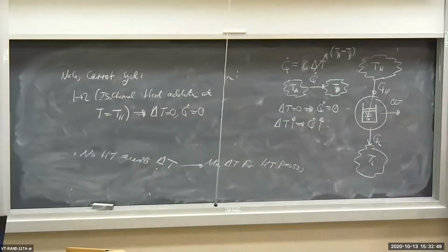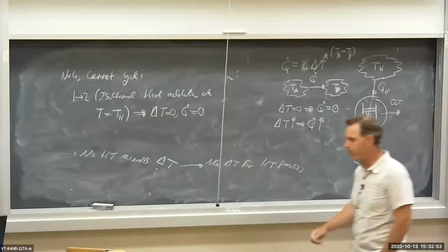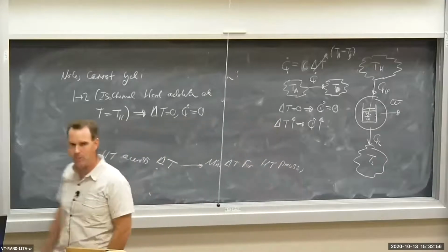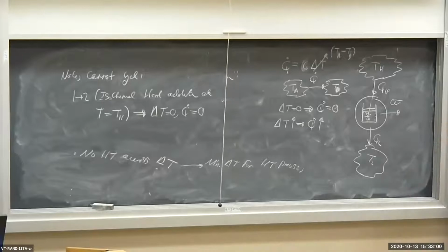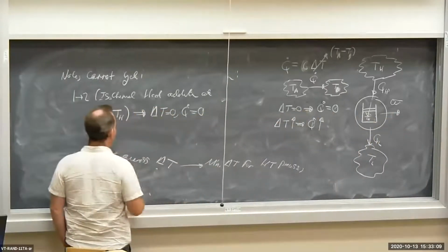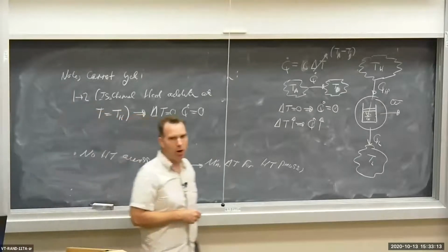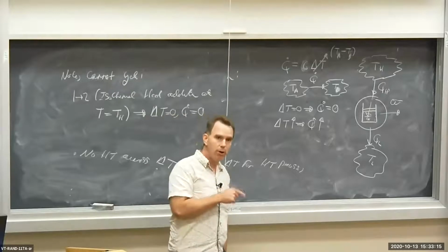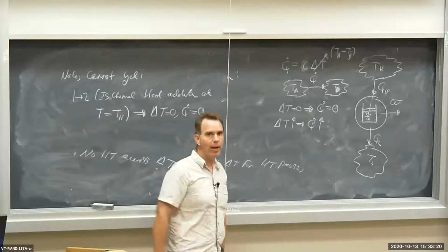So in theory, if we transfer heat from the high temperature reservoir into the working fluid and the working fluid is at the same temperature, in theory, Q dot, or the rate of heat transfer, is 0. So in reality, process 1 to 2 or any heat interaction for the Carnot cycle is reversible, but it results in a 0 rate of heat transfer.